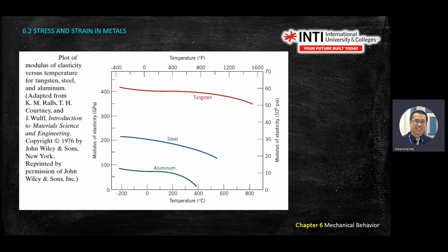We have E, so call out Hooke's law. The next step is normally Hooke's law. You write in the answer: Hooke's law, stress equal to E times strain. Stress is force divided by area, and strain is change in L over L0.